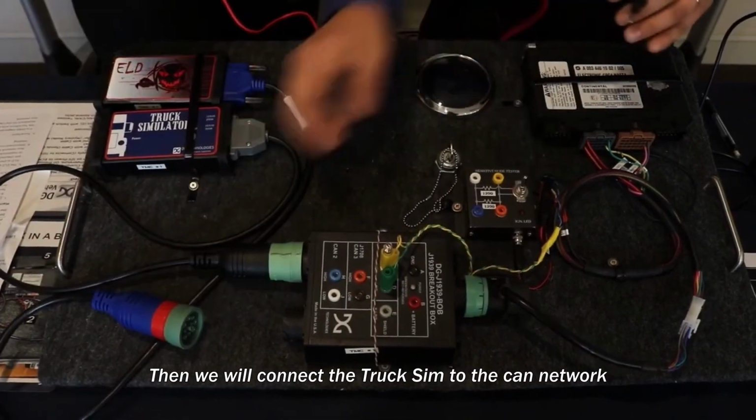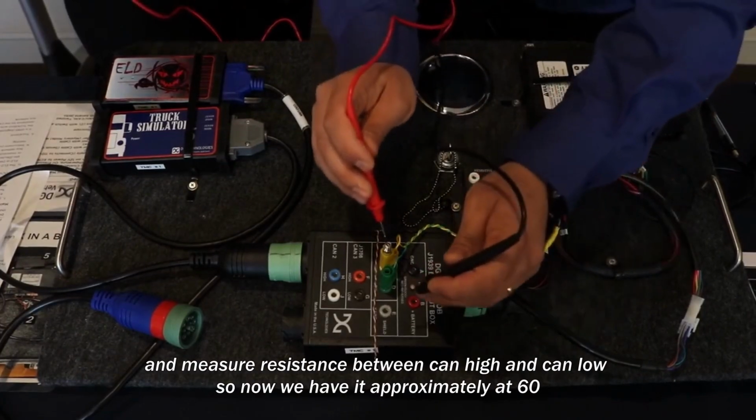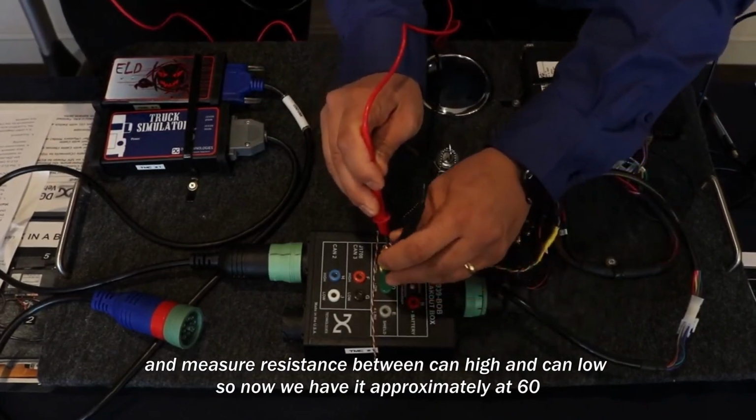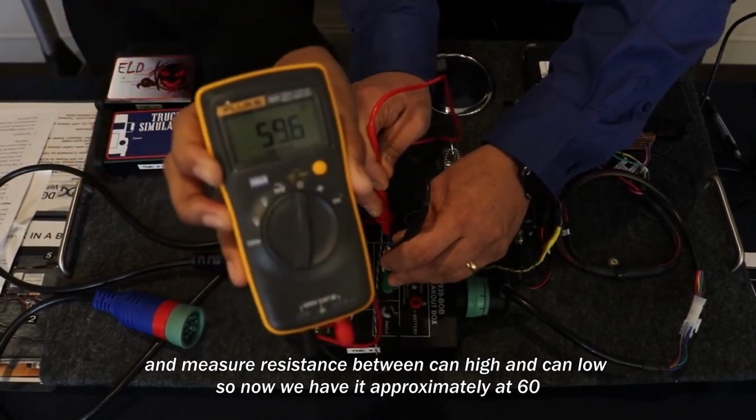Then we will connect the truck sim to the CAN network and measure the resistance between CAN high and CAN low. Now we have it at approximately 60.